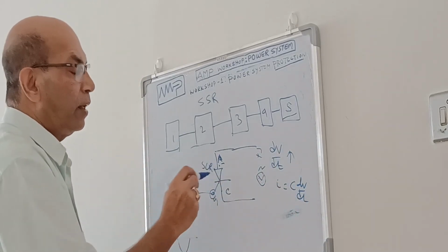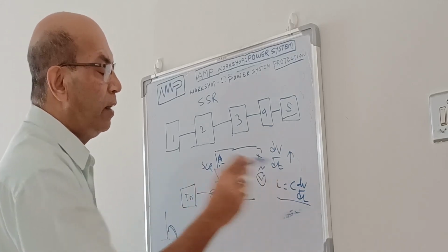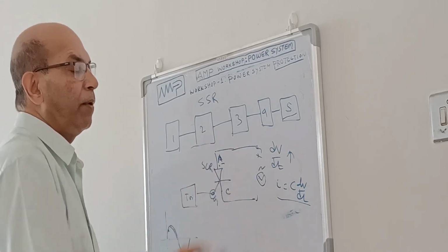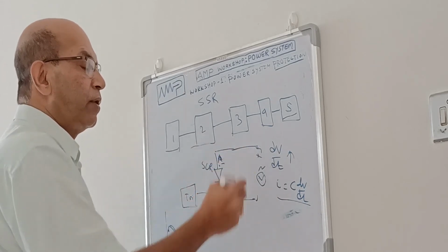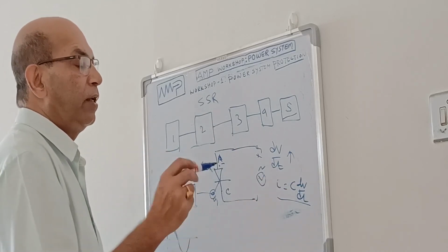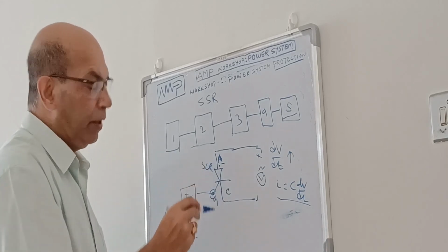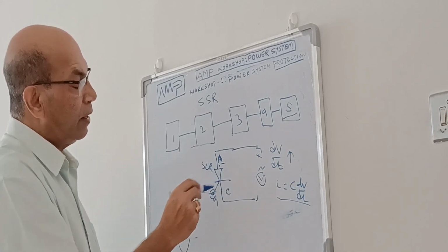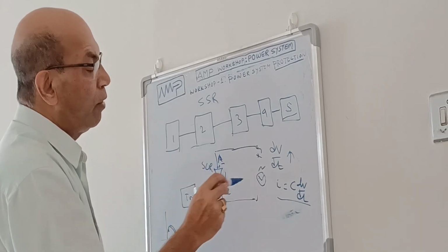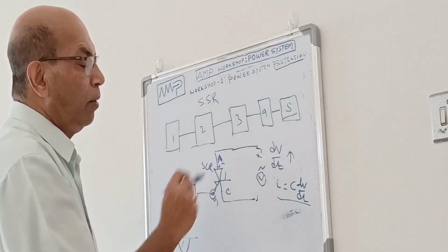When it is in the non-conducting stage, when it should not conduct, this stray capacitance and high dV/dt come into play. This dV/dt can come out due to switching operation, or can be caused by change of voltage, in a steady stage or in a dynamic stage. If this dV/dt comes with a high value, then immediately current will flow through the gate and anode, which causes triggering of the gate signal, and the anode will conduct in the non-conducting stage when it should not conduct. Then the load will be burned out.